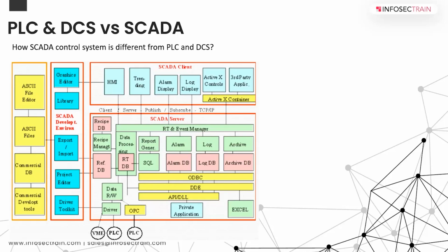When we talk about PLC, it's a feedback control loop directly controlled by the PLC. But when we talk about SCADA, the software monitors the overall performance of the loop. That's all. So DCS is a control device that has higher capabilities than PLC, as we saw, while SCADA is a software environment that can communicate with the PLCs and at times with DCS also. It depends.